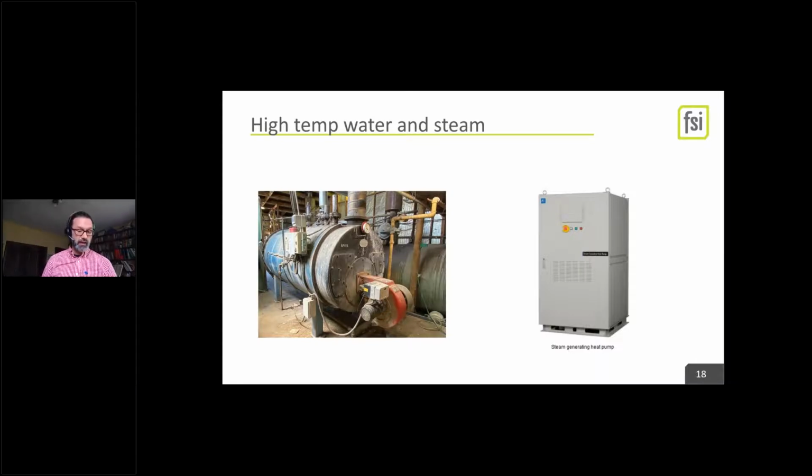But yeah, you can absolutely, if you've got a simple system, you can replace the coil, or if you've got a very complex, expensive system, like a built-up rooftop air handler that you're trying to keep most of, you can just replace the coil with one selected to 130 or 140 degrees. And honestly, with a heat pump chiller, I'd select to 130 or maybe even 125 so that I could run down to very low ambient, maybe not need the electric backup.